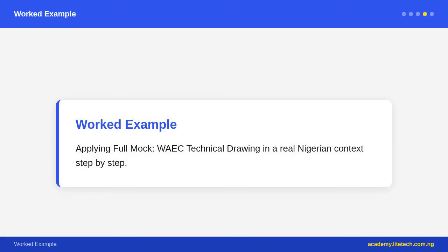Types. Deep groove ball bearing, most common, can take radial and axial loads, quiet, high speed. Cylindrical roller bearing, higher radial load capacity than ball bearing. Taper roller bearing, takes combined radial and axial loads, used in wheel hubs, gearboxes. Thrust ball bearing, primarily axial, thrust, loads only. Self-aligning ball bearing, can accommodate shaft misalignment.